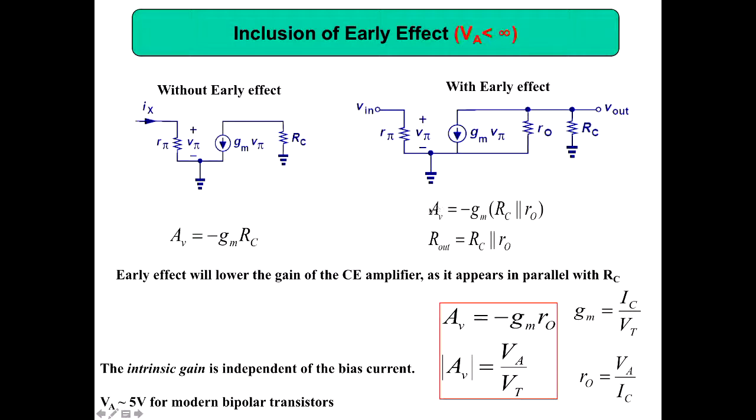So how can you increase the voltage gain? I want to increase the voltage gain. How will you increase it? Maybe one possibility is to put in a bigger Rc. But then again, there is a limit to Rc. It should not go into saturation.